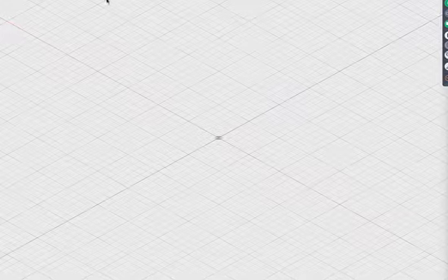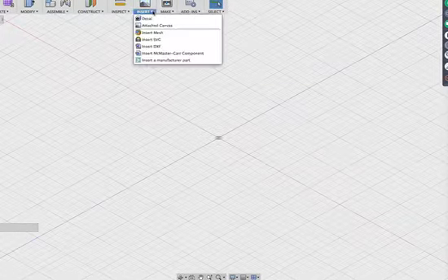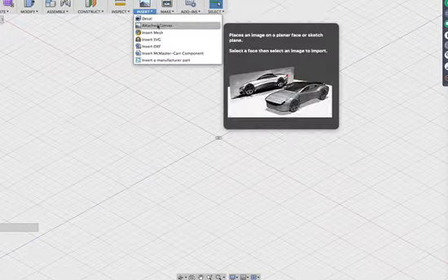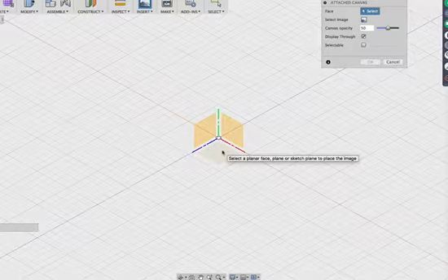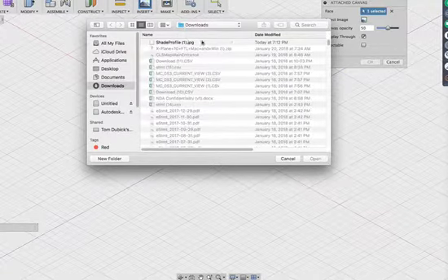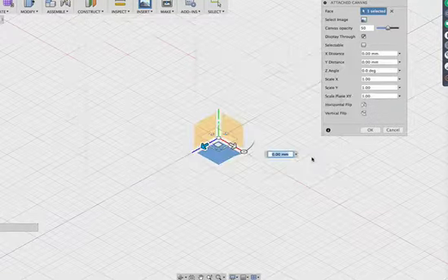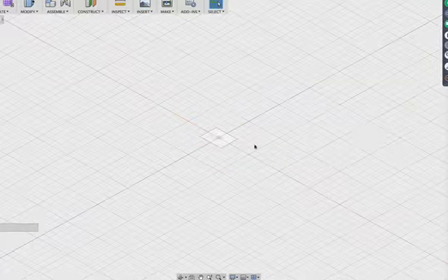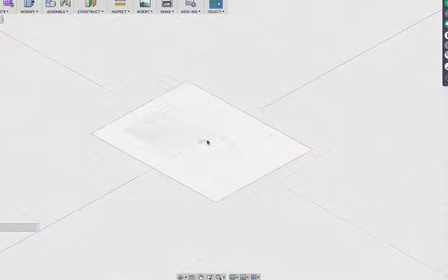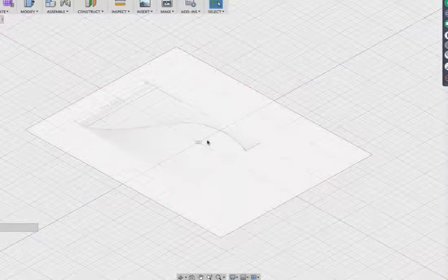So I'm going to go up here. I'm going to insert. Watch me do it, then you can do it. Attach canvas. Make sure you select this plane or face, because we're in kind of a sketch mode now. So make sure you select there. I select an image, shade profile. If you weren't here last time, it's under the handouts. There's shade profile Fusion 360. There's opacity. Say OK.